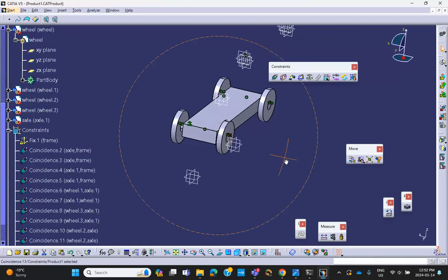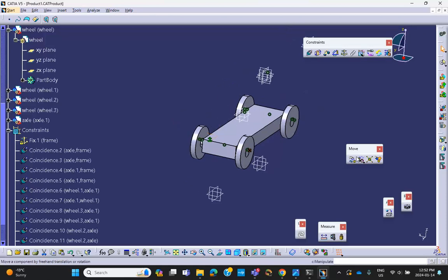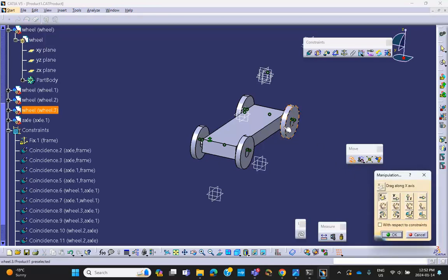So how do I know if the assembly constraints are good? If I move these things, separate them from each other, and update, they should go back to the proper position. For example, let me translate this thing in the Z direction, maybe X direction or Y direction. X is like that. Okay, good. And let's also do a crazy rotation to any one of these.